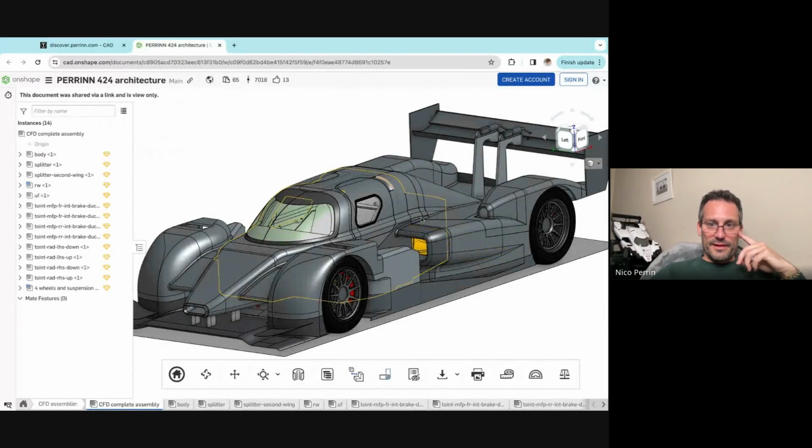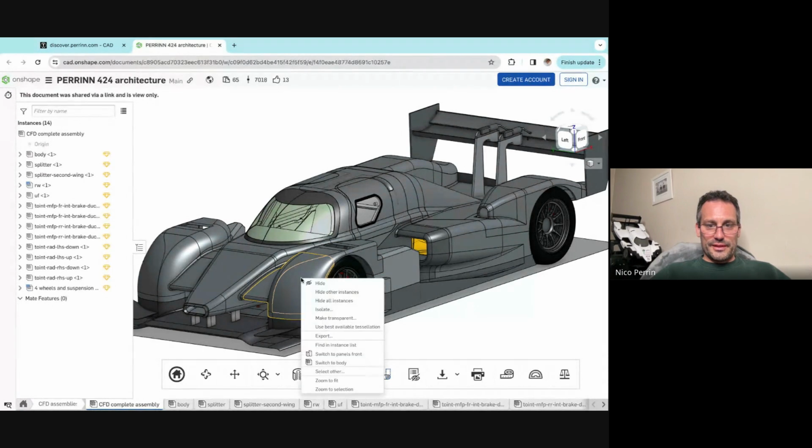Okay. From there, imagine you want to see how a certain part has been designed. Let's look at the wheel arch at the front. So let's right click here, and it will tell you that you can navigate to other tabs where this part is coming from. This is an assembly here I'm showing. And typically that specific component has been designed into another tab that's called panels front.